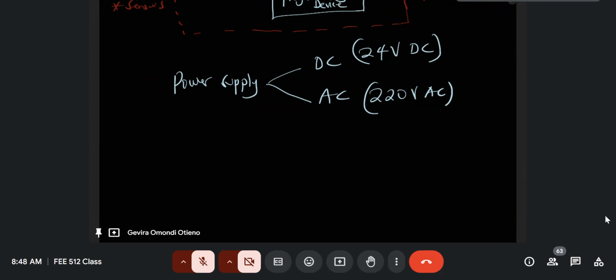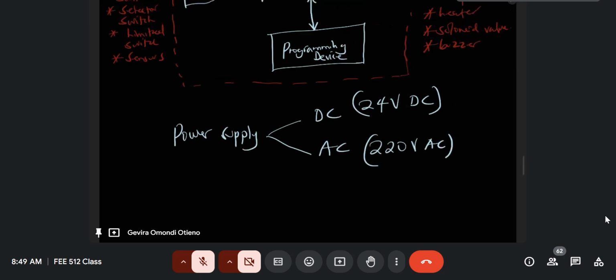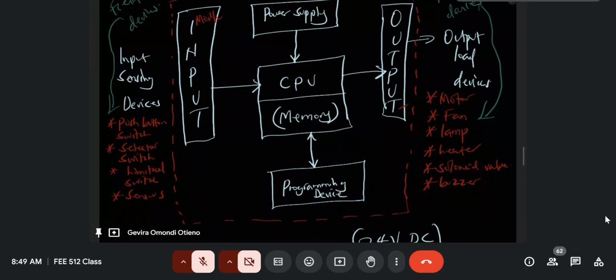What I must mention again is the input-output modules. Remember, the input-output modules are simply to convert logic inputs or outputs into physical actuation. You have a PLC, which is software, but then you have the hardware devices outside. In order to link those two, you need the input-output modules. So they are basically interfaces for input devices or interfaces for output devices. And we've listed them in our diagram here. So that should be very clear.